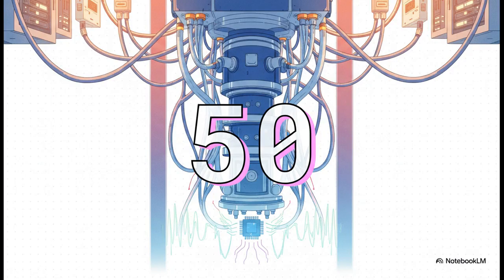The core of this problem actually comes down to standard engineering impedance, 50 ohms. The typical room temperature instrumentation we just looked at operates in the 4 to 8 gigahertz microwave band using standard 50 ohm coaxial cables. Now, to keep the qubit stable, the quantum chip has to sit at the very bottom of the fridge at just a few millikelvin. Guys, that is colder than deep space. But sending hundreds of microwave signals from warm room temperature racks down thick metal cables into a freezing environment, that creates a massive heat and noise problem. The cables leak heat and thermal noise straight down to the qubits, completely destroying their delicate coherence.